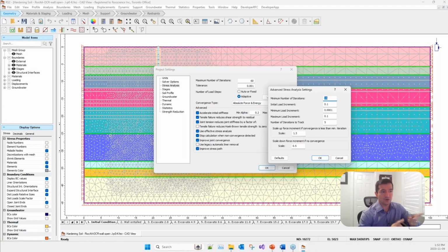What the adaptive option also gives me is that if, for any of these load increments that I apply to the system, I did not get convergence within a certain number of iterations, the simulation is able to go back to the previous increment where we had convergence and reduce the load increment. So it has the ability to recover from the past converged case, and it can continue by adjusting the load increment adaptively so that you can arrive at convergence. That would be my recommendation if I'm dealing with a simulation that has convergence issues.